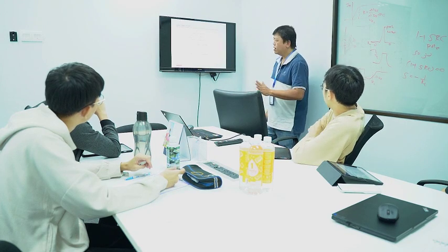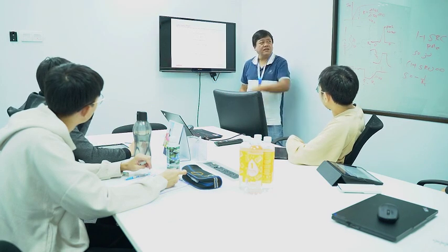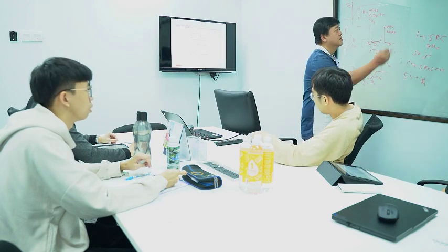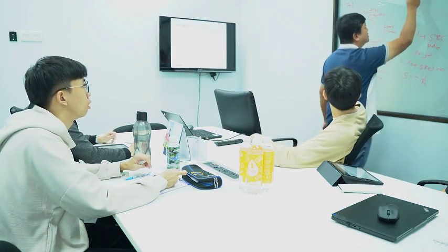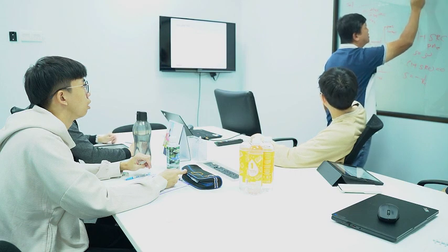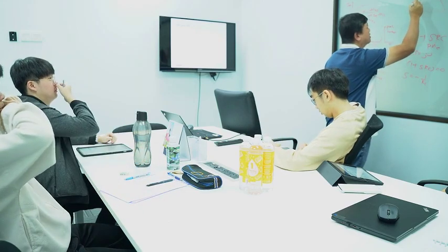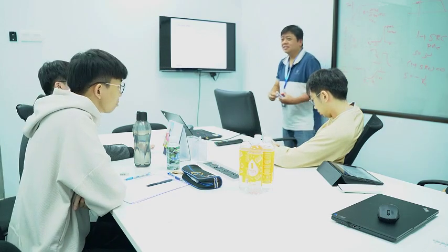Now I want to give you all a quiz. Normally, you find a cutoff frequency. At which point do you find the cutoff frequency? Negative 3 dB. This is gain, this is frequency. You always say minus 3 dB, correct? Now the quiz is: why minus 3 dB? It's the point where, if you go beyond it, you will have more phase shift.